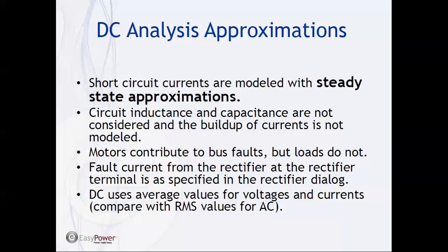DC motors contribute to bus faults, but loads do not. So entering the motor resistance in the dialogues is important for short circuit calculations. When we model rectifiers, we have to enter the fault information in the rectifier dialog. And lastly, when we're talking about DC values, these are average values and they are slightly different from what we typically refer to for AC systems, that is RMS values.